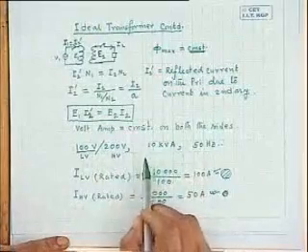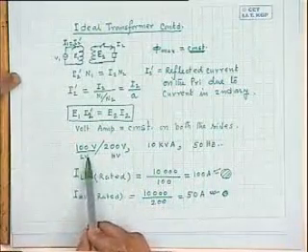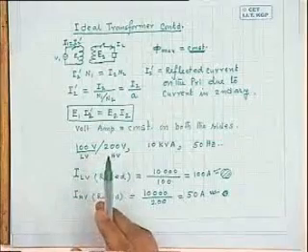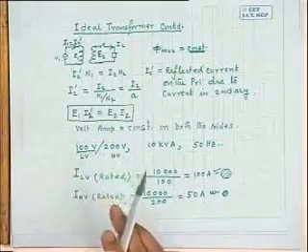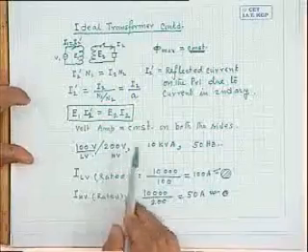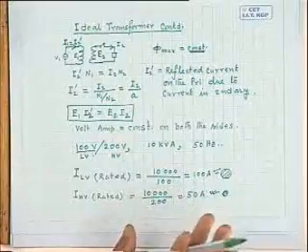It has to establish the same flux. Remember that in a transformer of this rating, you should be very clear about it. Suppose you decide that I will connect the LV side as my primary. You apply 100 volt, 50 hertz. On the secondary, that is the HV side, I will connect a load. There will be some flux level established in the core.